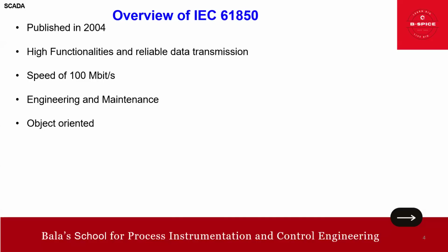Then what is peer-to-peer communication? Peer-to-peer communication for fast data exchange between feeder-level devices, that is the protection devices and bay controller, is supported by GOOSE, that is generic object-oriented substation event.